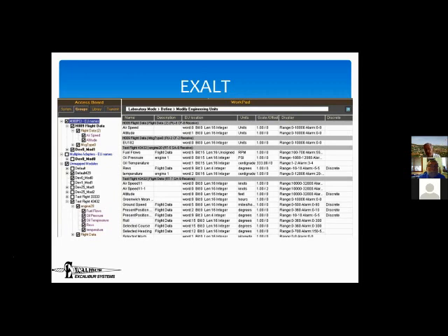It's not designed for that kind of length. So you really want to get the data on the CAN bus and then transfer it to an AFDX. And the AFDX will run an Ethernet wire to the cockpit, which is certainly capable of doing. So the idea of having multiple data sources on an aircraft is not at all unusual. And that's one of the many things that Exalt is designed to handle.